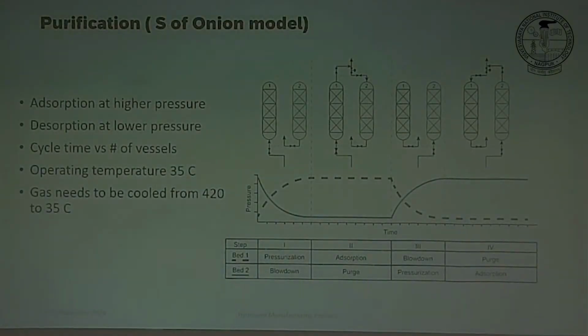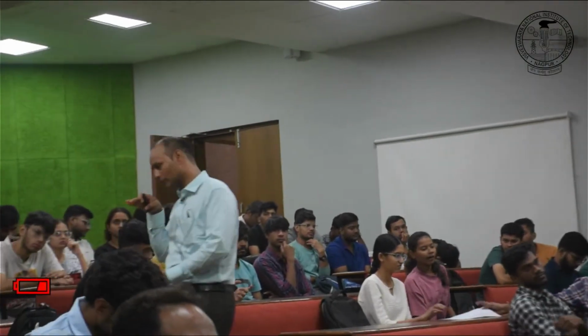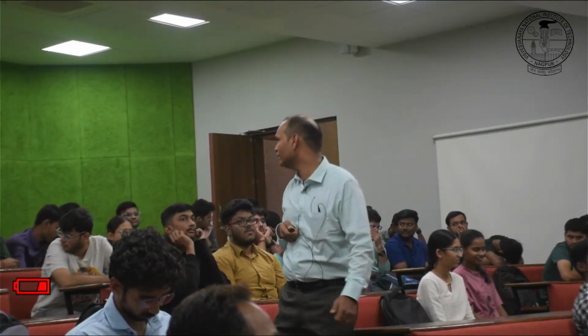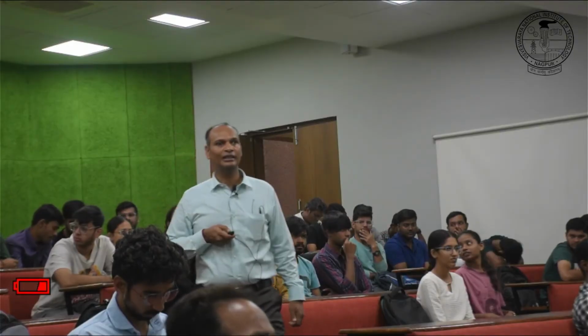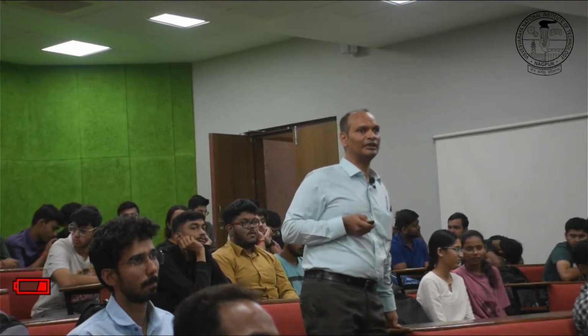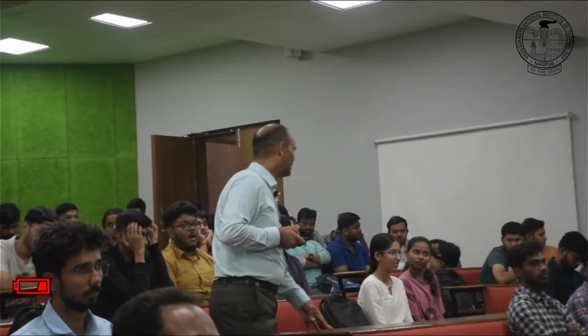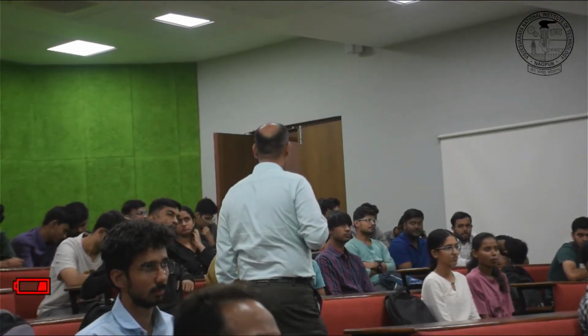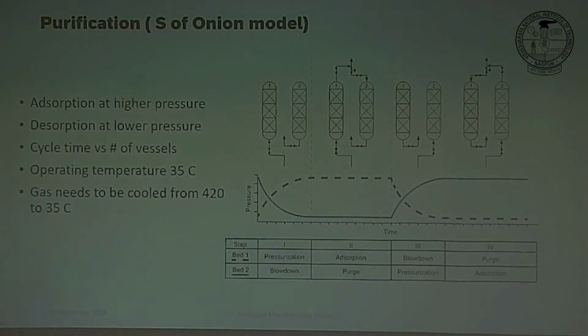So at a certain point, you will not have any pores which can adsorb any more gases, right? What you have to do, once again, is a trade-off between operating cost and capacity cost. If you make your vessel very big, you can adsorb for a longer period of time. But if you make it smaller, within minutes this bed is already charged with your byproduct gases. So normally, the optimum size of these beds is somewhere around 12 to 13 meters height and 3 meters diameter, and they get saturated not in days, not in hours, but within minutes.